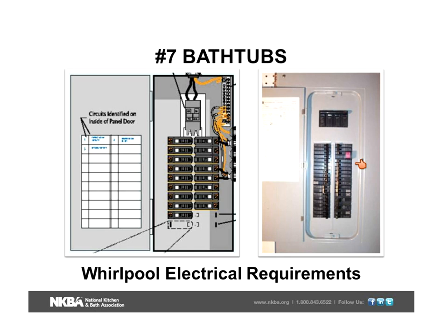And again, don't add the breakers up because each breaker will have an amp rating. And I'll guarantee you this is well over 200. So you're not adding the amperage of the breakers up to see if it equals 200 or less. The main thing we have to worry about as kitchen designer is, do you physically have the room? It's very difficult to overload one of these unless every single one happens to be for maybe a 50 amp heating unit in every single room. But that's how you would determine the panel size. But the most important thing is simply, do you have physical room in that panel?